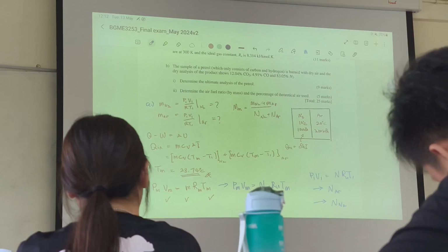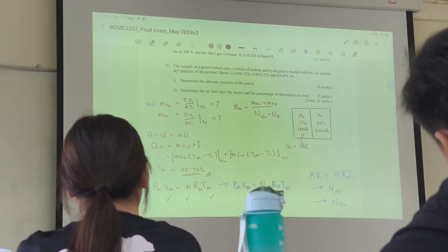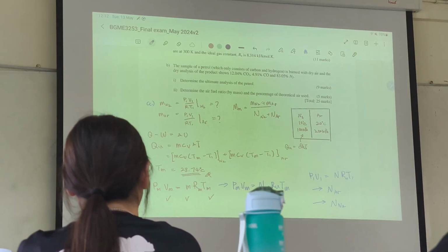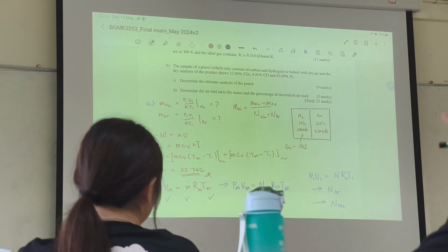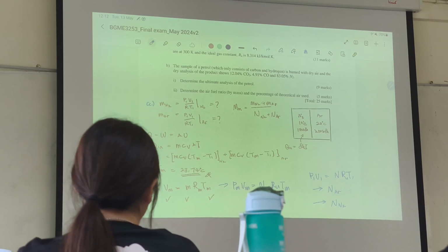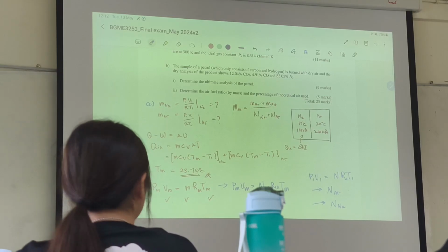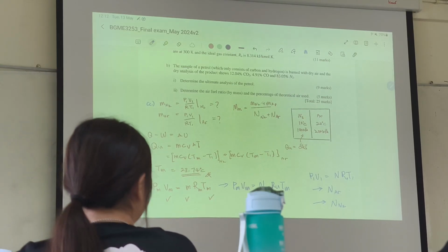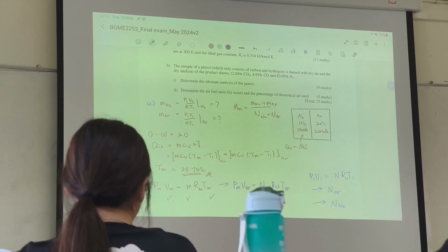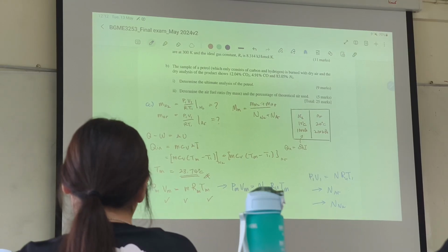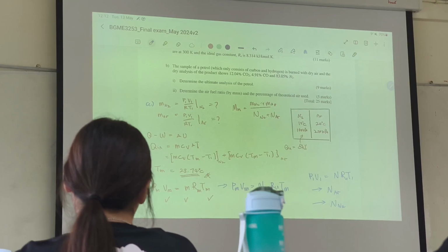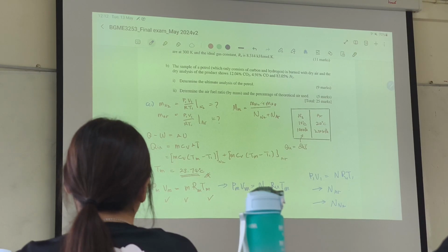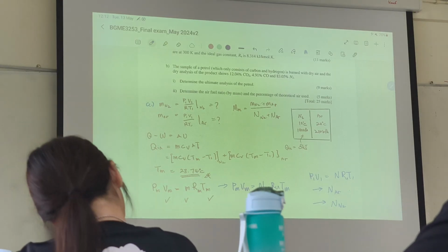Like I said, it's 3 steps here, because my solution here identified mass, I just took the answer. So this should be the first step, for the mass. Mass you still need to find because otherwise, right, you cannot do QE. Technically speaking, you can do QE, but I don't think you have the table, because the table gives you CV, but not CV bar. If you have CV bar, then you can skip the mass totally. But I don't think the table has that.